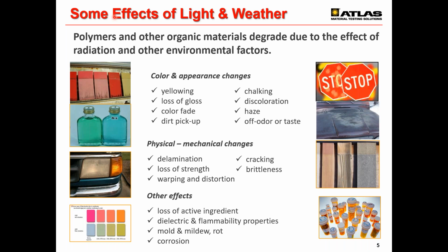So the polymer, the coating becomes mechanically weaker. So very often you observe that materials get brittle, surfaces crack, or you see delamination, in general a loss of strength of those materials. And there are a lot of other effects related to weathering degradation.